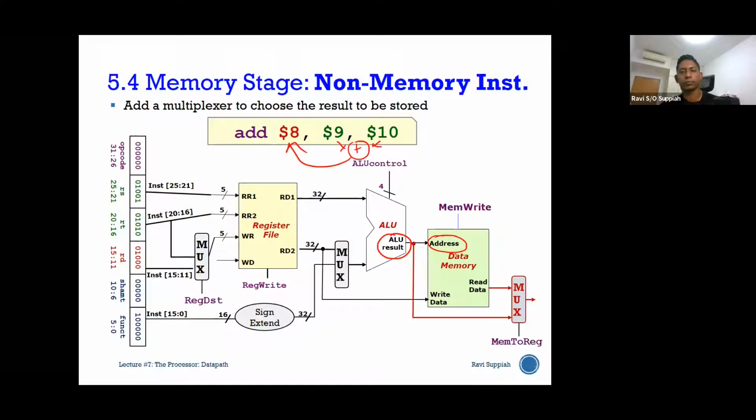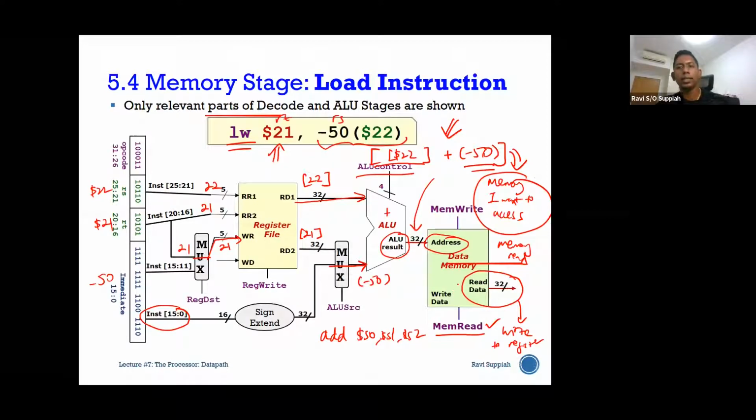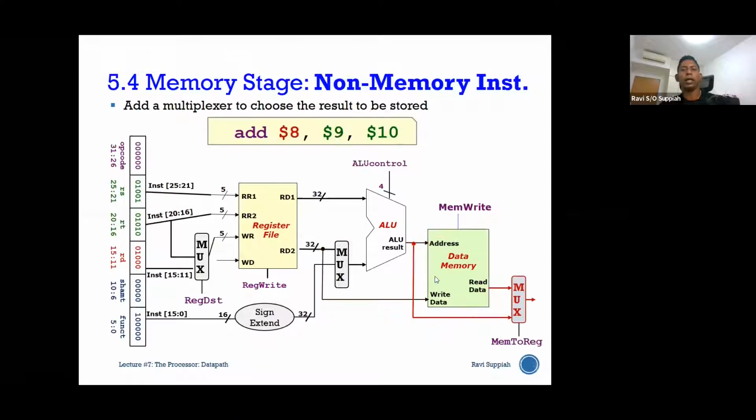All right, so in order for me to take this data and channel it back, if you look back at this instruction and this instruction, you will see that in both these instructions, I'm taking some information and I need to write back to a register. All right, but for a load instruction, the data is coming from the memory. In an R type instruction like this, the result is the ALU result itself, nothing to do with the memory.